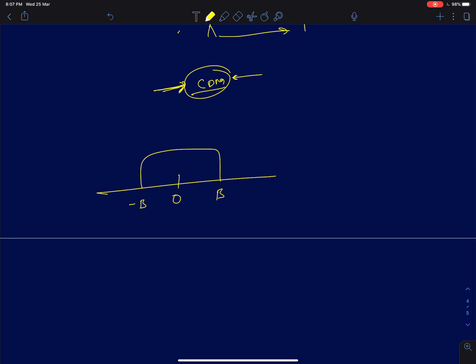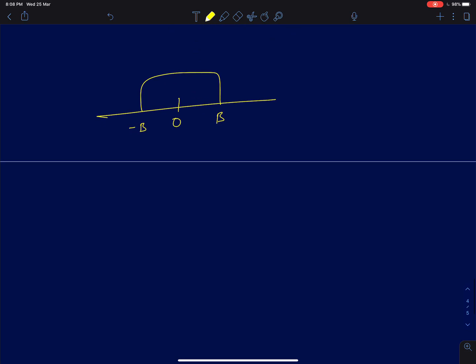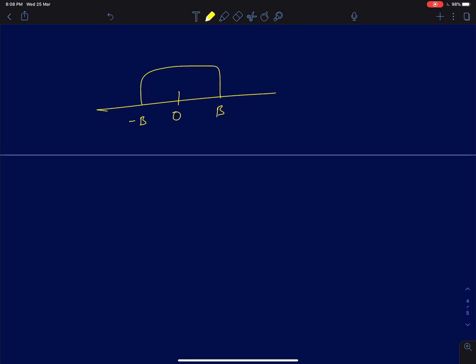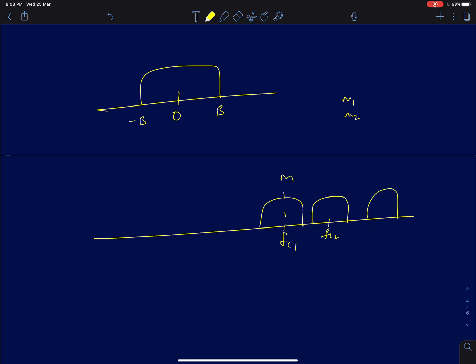Frequency modulation also comes with another benefit, which is what we call frequency division multiplexing. Instead of upconverting all the M message signals to a single frequency, I'm going to upconvert each message signal to a different frequency, FC2. So M1 will be here, M2, M3, and so on. Each signal can be upconverted to a different frequency. So by doing this, I can transmit.